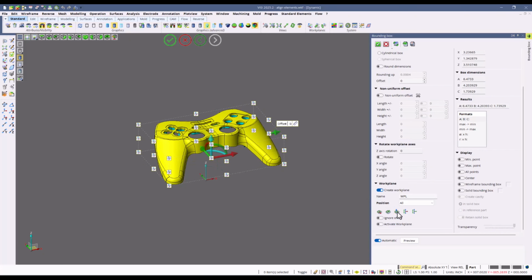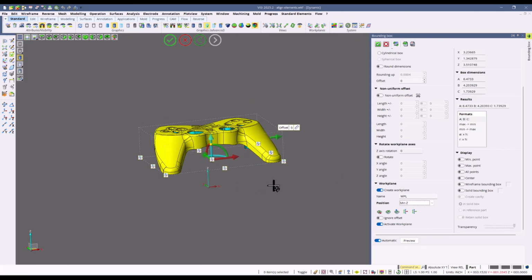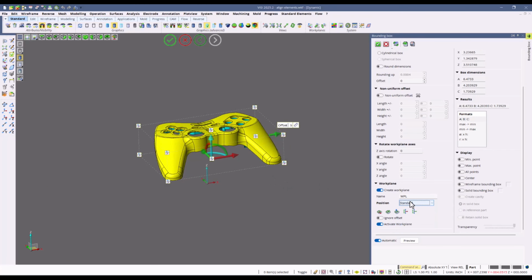So it makes it real easy to just flip, mirror, make that workplane active after you're done. You also can change it to different styles to show what points are available, depending on if you just want to get the bottom of workplane at the bottom, standard, or all.